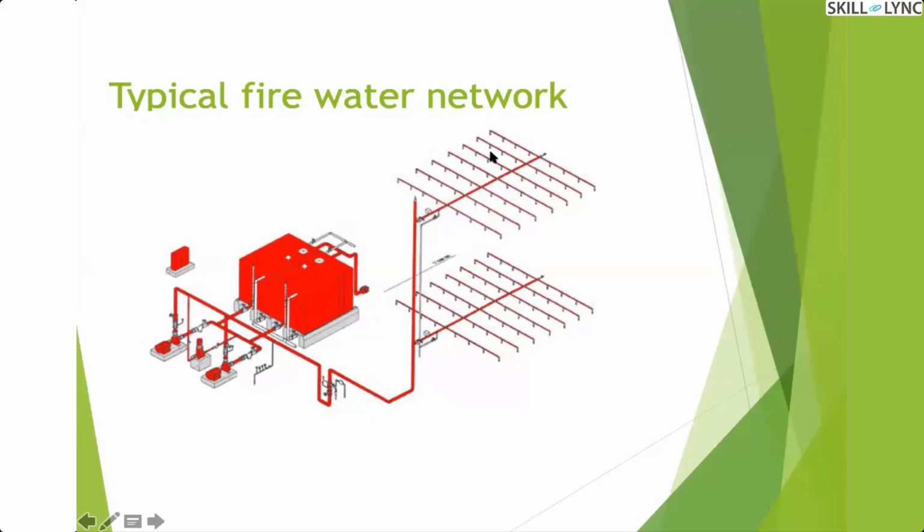So for that, hydraulic network simulation will also be helpful. If you have to solve manually, then you will solve the manual way to determine the pressure here. But then when a flow starts happening, there will also be flow rate. If you calculate manually the pressure drop up to this point, you will calculate the pressure at this location and the flow rate. But actually what happens is when the entire flow flows, there will also be flow rate which is going to go out through these nozzles.